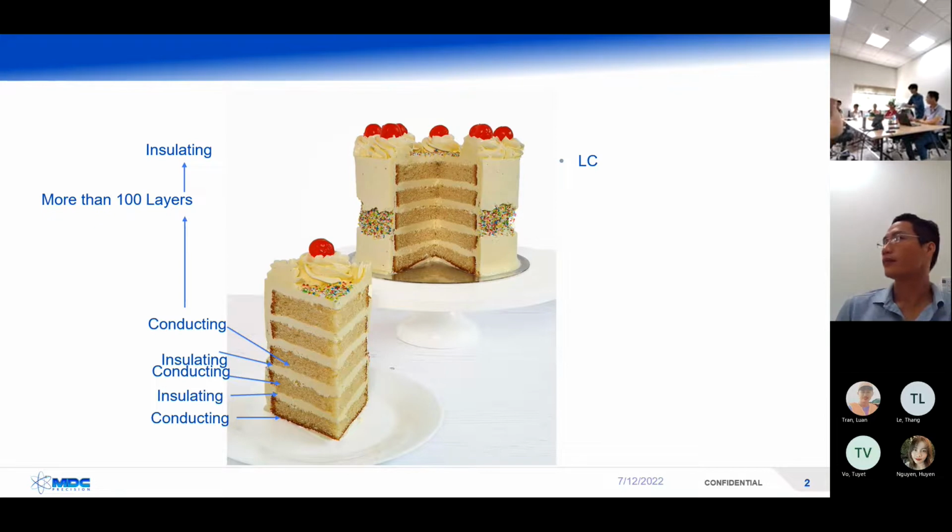So the vinyl outside keeps it so that if you have two wires near each other, you don't have electricity go from one to the other, right? Does that make sense for everybody? It will be separated. For a semiconductor, because we're making them so small, we can't run a bunch of wires. So we actually have to make a conducting layer, and then we will paint or etch out the wire form in that conducting layer.